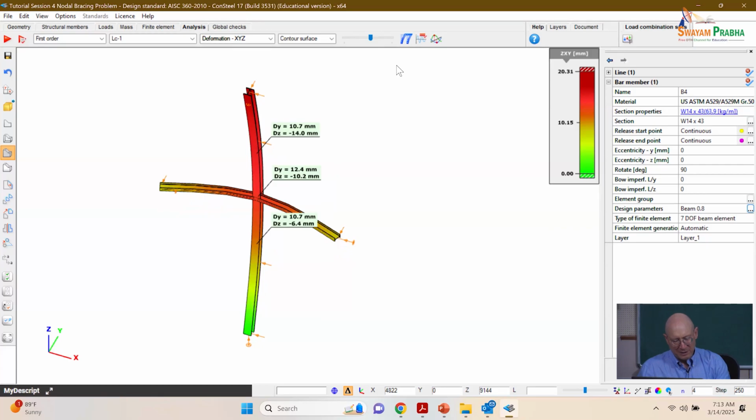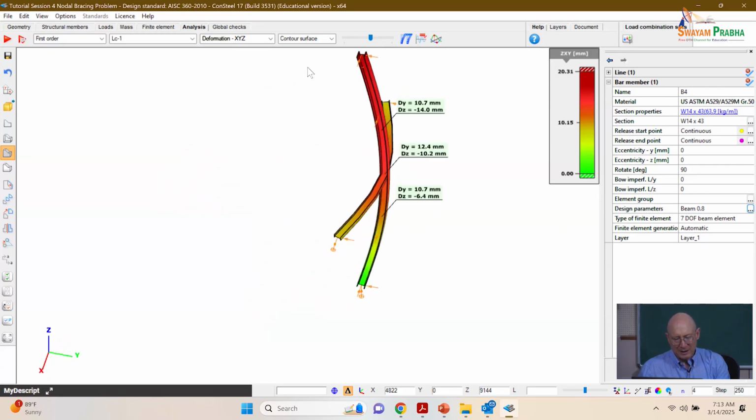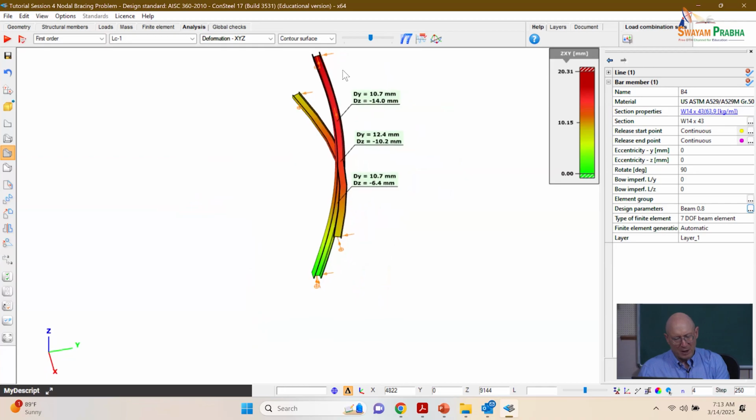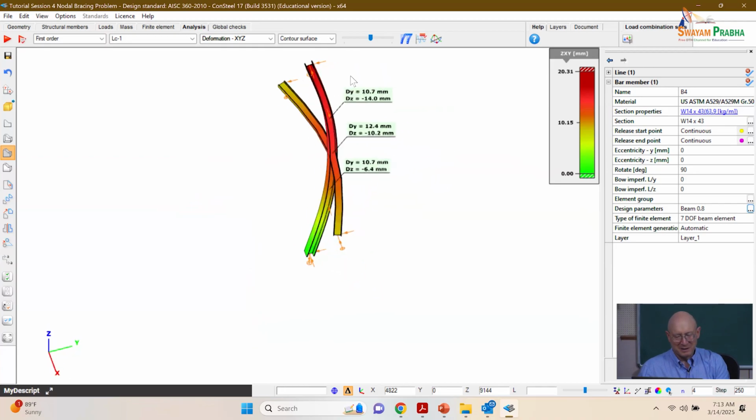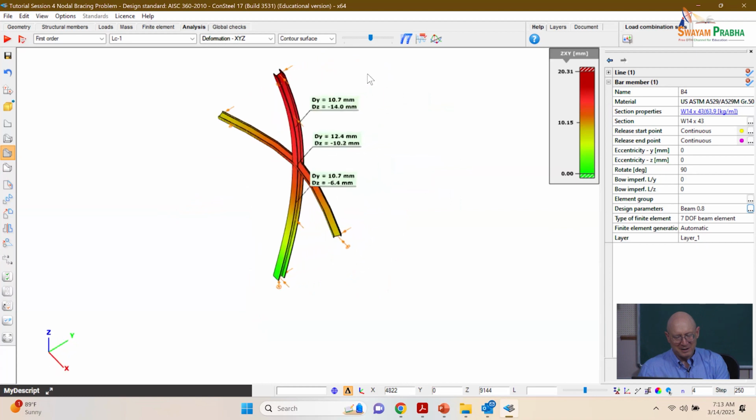It's apparent that I'm getting some help from that flying beam, but it's not really holding that point as if that point were braced, right? It's what we would call a partial bracing to that point. But hey, if I've got some stiffness and that's enough to where I can make this problem work with a lighter brace, okay, then good. I used 2 sizes smaller on this flying brace.